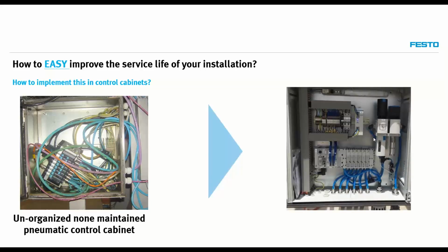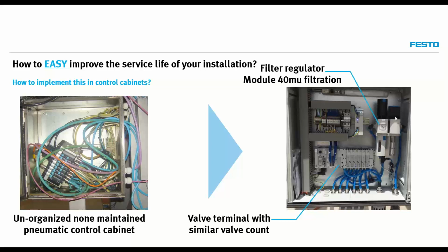Again, we will start with the same basis as the valve terminal with a similar valve count. But the second part we add in the control cabinet is our filter regulator. It stabilizes the pressure, but it also adds an additional level of filtration so that the components after this unit are protected from any type of particles and first hits of condensated water in case it's happening. In terms of safety,